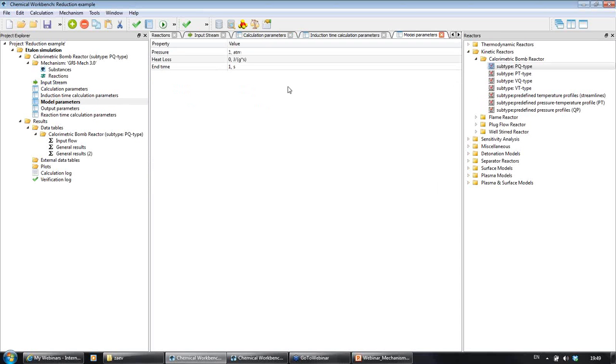Also, this mixture is placed at conditions of 1 atmosphere, and I need to simulate the ignition delay time. So my target for the simulation, even for accurate simulation, is the ignition delay time. I guess that the existing GRI mechanism is a detailed one to solve this problem, and I can reduce its complexity by removing redundant species and reactions.